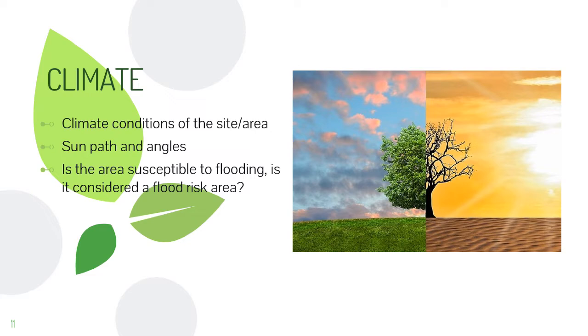In Cebu, we are vulnerable with landslides and erosion during heavy rains because of the type of soil. For areas near water or facing the ocean, these areas are vulnerable to storm surges during typhoon. So some information is not freely available, but a client or their legal representative should be able to clarify any issues regarding right of way, right of light, legal easement, and any rights of tenants. There are many more things to look at, and each site is very different, but hopefully this will give you a starting point for getting the best out of your site visit.